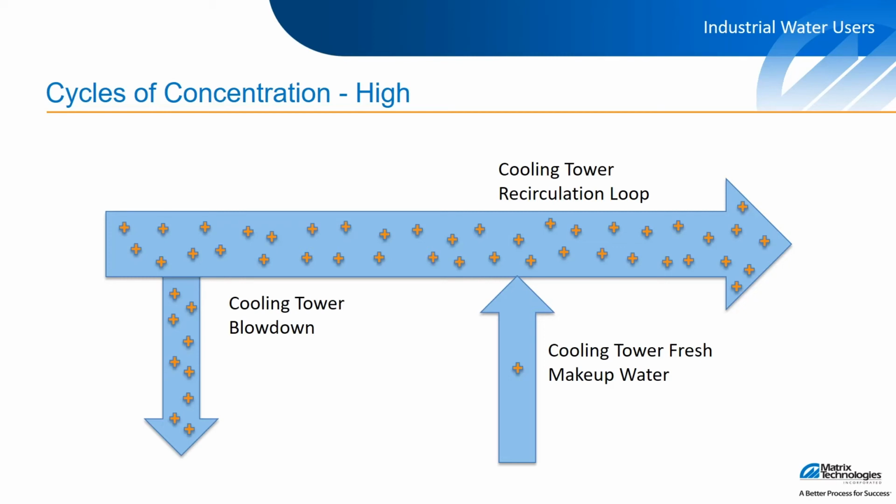Of course, some flows are non-negotiable, like safety shower or boiler water, which brings us to the second way to reduce your water bill. Maximize the water you do consume. For example, steam condensate provides high-quality hot water to be reused within the boiler system or elsewhere in the plant. The steam was already fresh water you paid for. Reusing the condensate for another use reduces fresh water flow and reduces effluent flow, both of which have associated price tags.